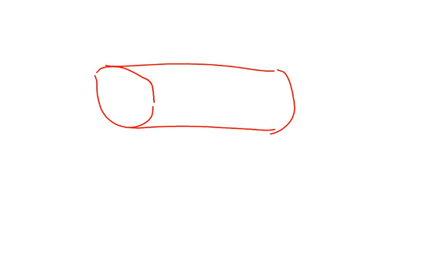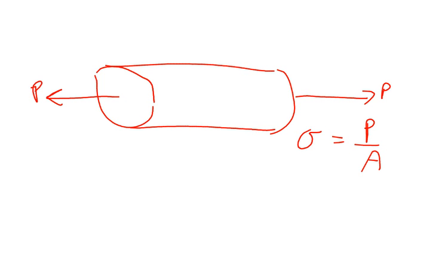So if I had a regular circular rod, we talked about pulling it in tension or compression, and the equations that are relevant here, you might recall, are stress is going to be force P divided by cross-sectional area A. Okay. Strain is equal to the deformation or elongation divided by the original length.